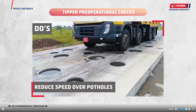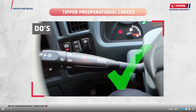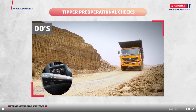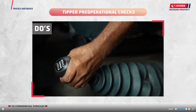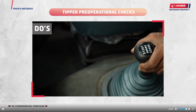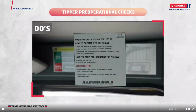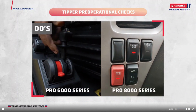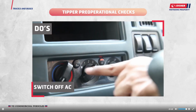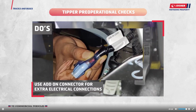Reduce the speed well in advance while driving over potholes. Always use the engine exhaust brake while driving downhill to avoid engine overrunning. Select the gears according to the load, road and speed condition. Keep a safe braking distance from other vehicles. Follow operating instructions before engaging the PTO, that is, power takeoff. Switch off the AC system when not required. Use the add-on connector for extra electrical connections.